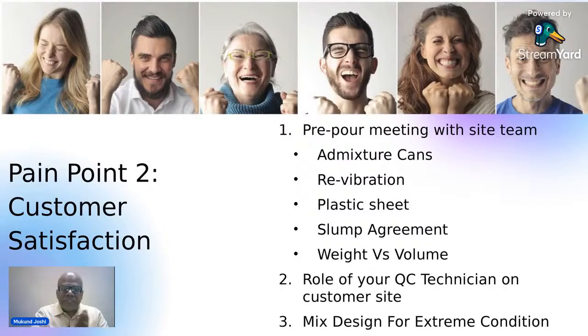Also, another point we will speak about in more detail is, can you design your concrete for extreme conditions? We know that in metro cities the traffic jams are going to be there, and how you are going to handle these traffic jams. Can you design your concrete with longer slump, longer retention? We have in our concrete this fantastic standard deviation. We did one fantastic session on that a few weeks ago in our Wednesday sessions, so just go through that session again on standard deviation. We need to use that.